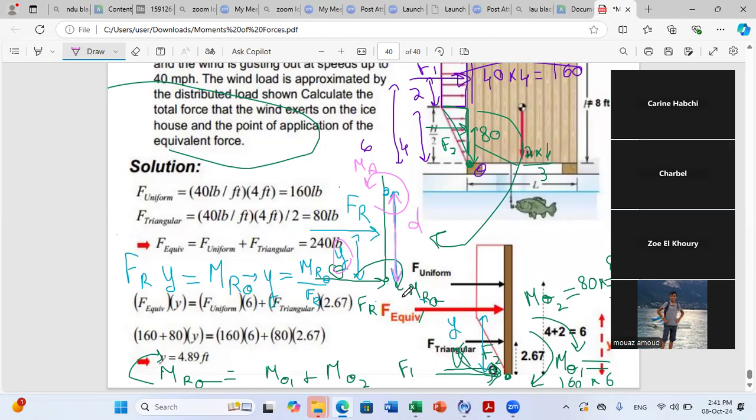Then we said that what if we want to displace the force in a way to produce itself this moment about O? That is, we don't need then any additional couple to have an equivalent system. If I ask you what is the position for FR to just reduce the system to a single force, you tell me I should move it a distance Y in a way to create about O which moment?